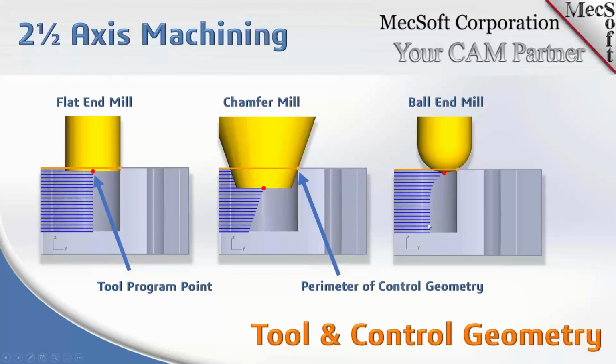Go ahead, Joe. Yeah, quick note on the ball end mill. Actually, 2 notes. What we're looking at here in the profile that Don has just shown, we call this the waterfall effect. So you can think of it as the tool is contacting that edge and it's waterfalling over that edge. And the middle picture, we call that the chamfer effect. Again, the same thing. It's contacting the side of the tool, and you're seeing that chamfer.